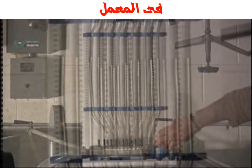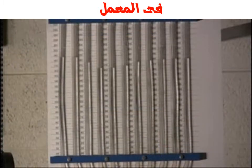Reduce the flow by closing the valve slowly, such that the difference between the highest reading at piezometer A and the lowest reading at piezometer D is about 2 centimeters. Now take note of the reading at station D for the minimum flow.